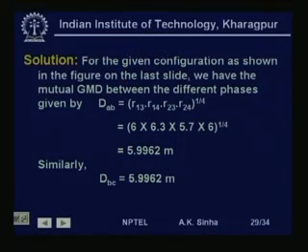So, this is the question that we will have to find out the inductance per phase of the line in millihenry per kilometer and millihenry per meter. We will also need to find out the inductive line reactance per phase in ohms per meter at 50 hertz. So, for this system, what we have to do is we have to find out the equivalent distances.